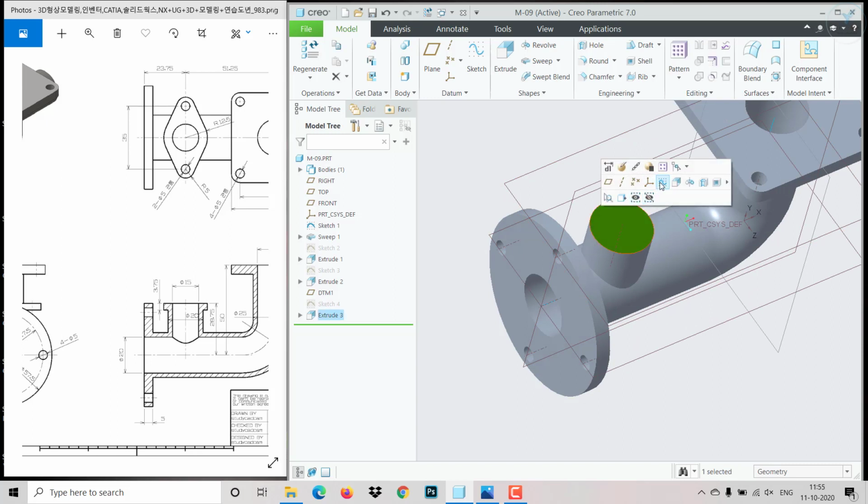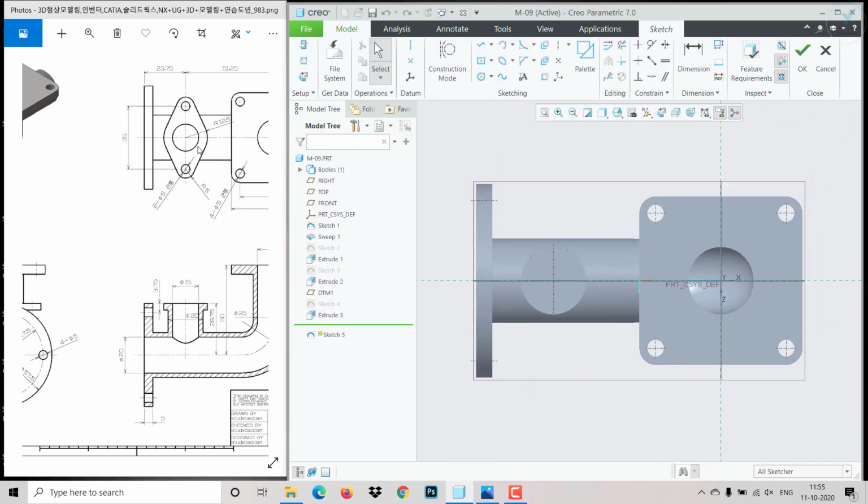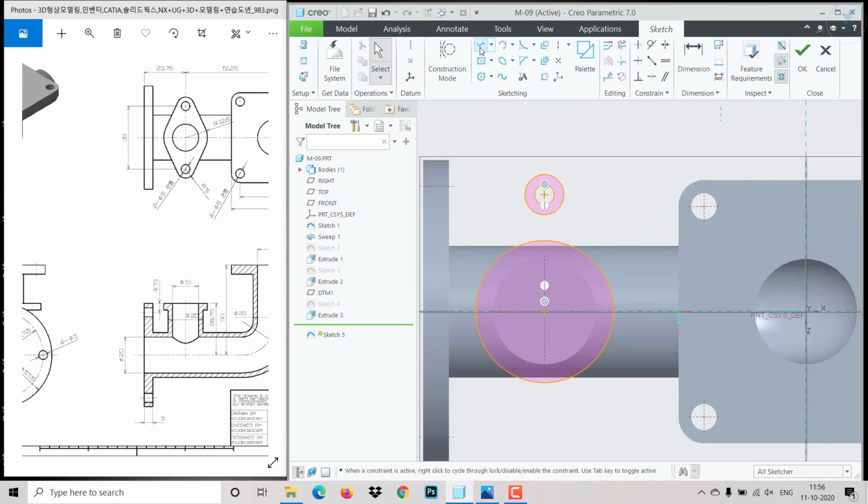So on top we need to make another sketch, that is over here. So first make this outer part, then finally we can make this hole. So click on circle, choose the center point, place a little bit outward on the same, one more circle like this. So then you can draw a line tangential. So those things we can do once we finish it. So this circle is having a radius of 12.5. Click on this, 12.5 created, and this distance is 35.